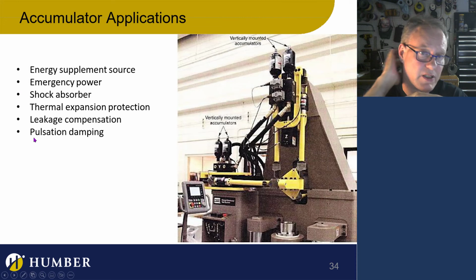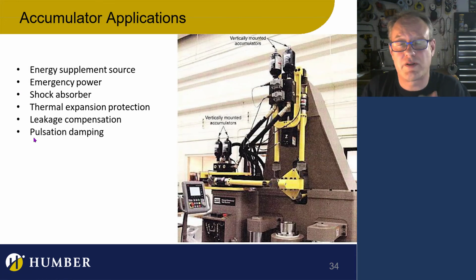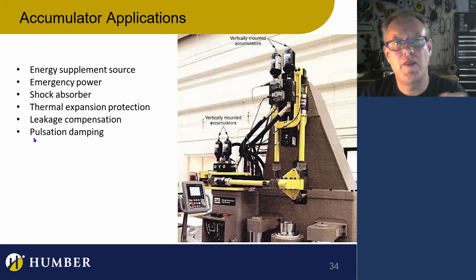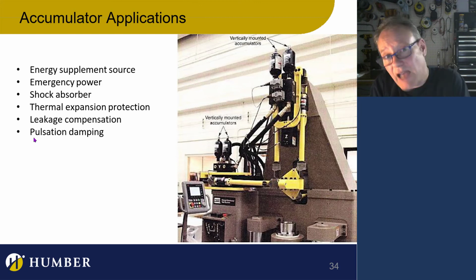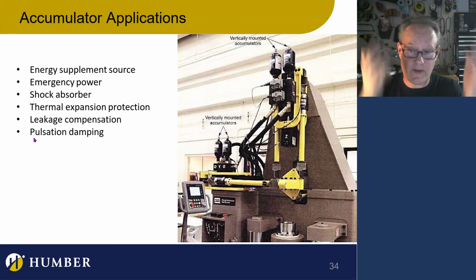There you go. So let's take a look at this. Energy supplement, to store the supplement energy. To deal with surges in the system as well. We'll talk about where surges can happen, and why you may want to be able to supplement the pump. Just give the pump a little bit of help when it requires just an extra little bit. An accumulator is really good for that. Emergency power, same thing with pneumatics. We did one of the labs in pneumatics, and we talked about the fact that an accumulator is good.